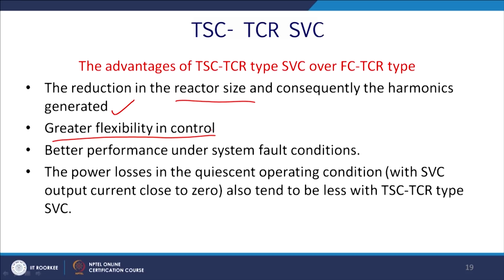Power losses in the operating conditions, that is with SVC output current close to 0, tend to be less with the TCR type SVC than the normal one.